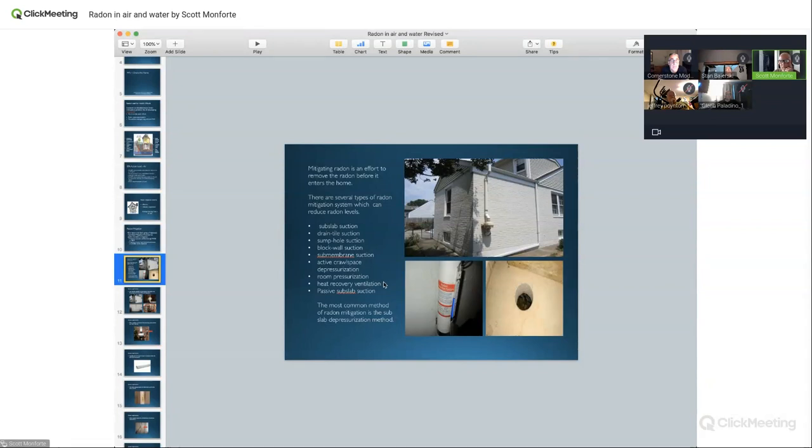Heat recovery, maybe count on the hand 5 times. Very expensive. You got to have balanced air in, out. You got to have air going in, air going out. So sometimes they can put those on the HVAC systems, but for mitigators, I would say subslab, submembrane are most common, and that's what I do most of the time.